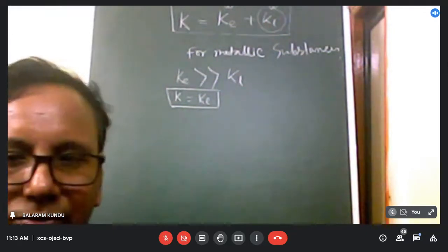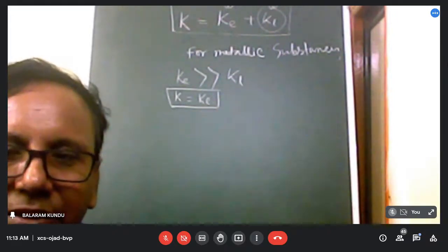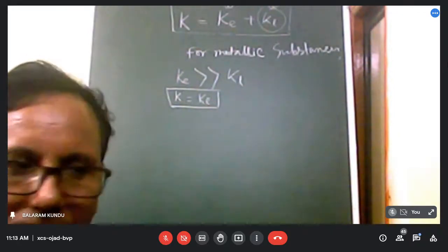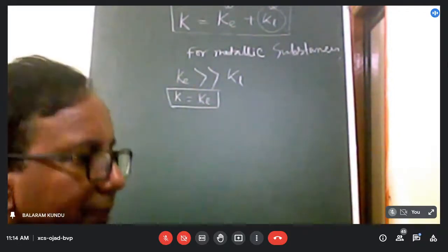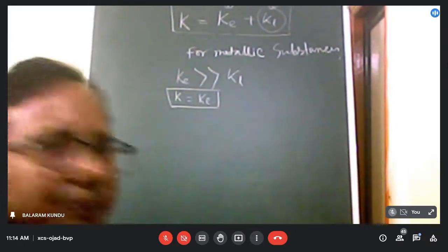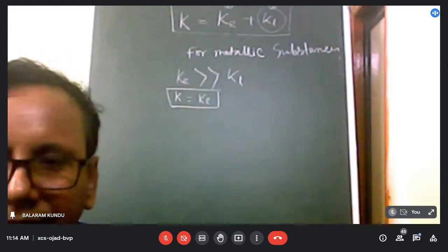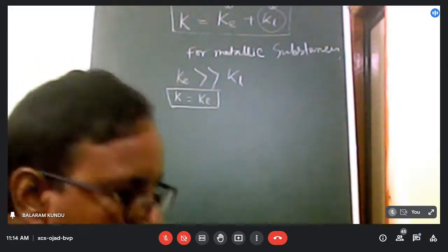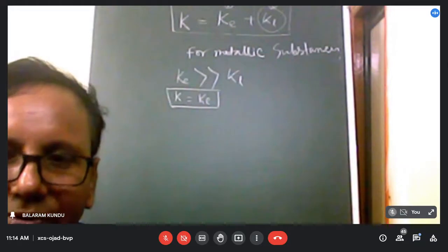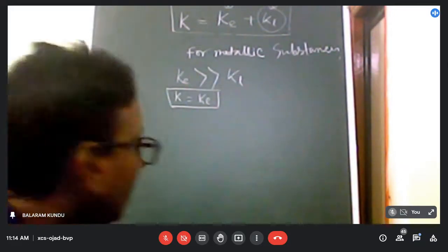So resistance to heat flow increases. As a result, thermal conductivity reduces, in all cases except aluminium, as I mentioned. So the heat transfer contribution due to free electrons reduces with the increase in temperature in normal situations. And in cryogenic temperature, the reverse phenomenon occurs.